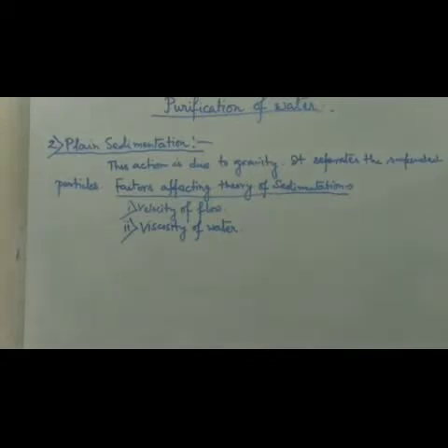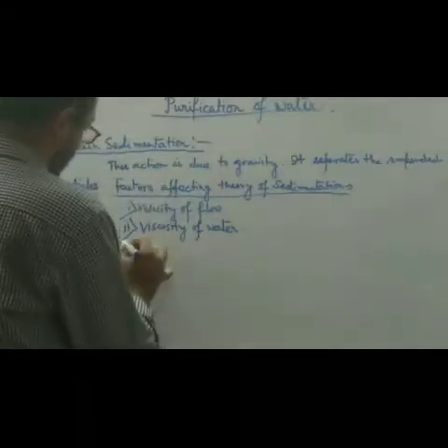The viscosity of water varies inversely with the temperature, so warm water is less viscous and it offers less resistance to the settlement. The next factor involved mainly is size, shape and specific gravity of the particle.